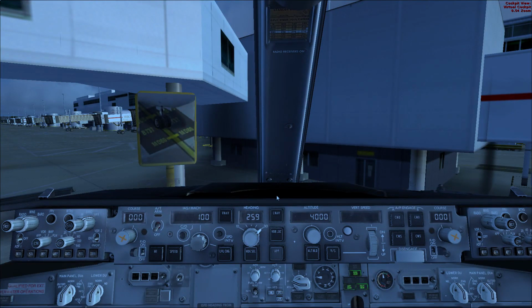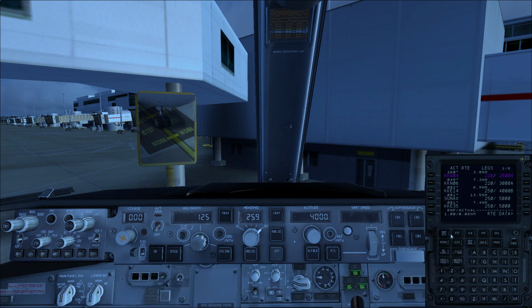It should actually say on the departure chart is your V speed. So we're going to set our V2 speed. You need to put your V2 speed here. Some airlines use V2 plus 10 knots for certain reasons. Some use V2 plus nothing. Some use V2 plus 15 or 20. I think 20 is the maximum. But we're going to take off with just V1 speed.